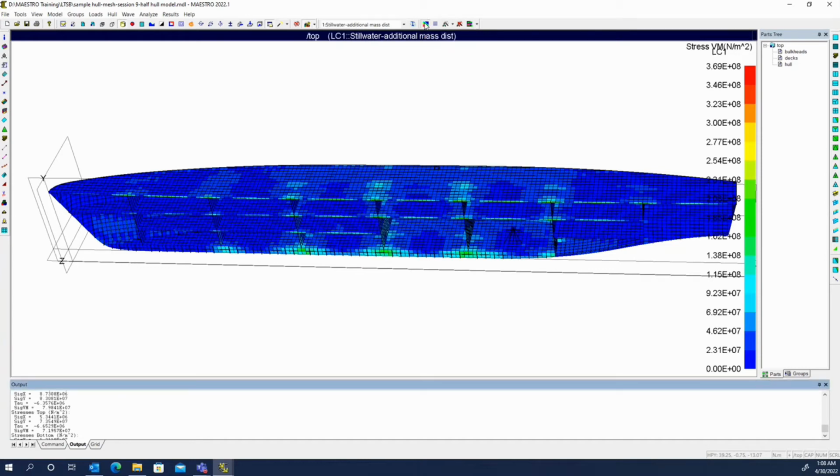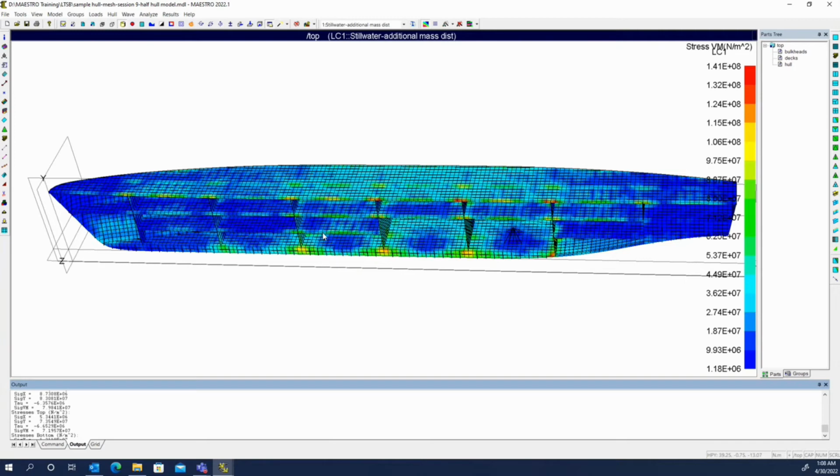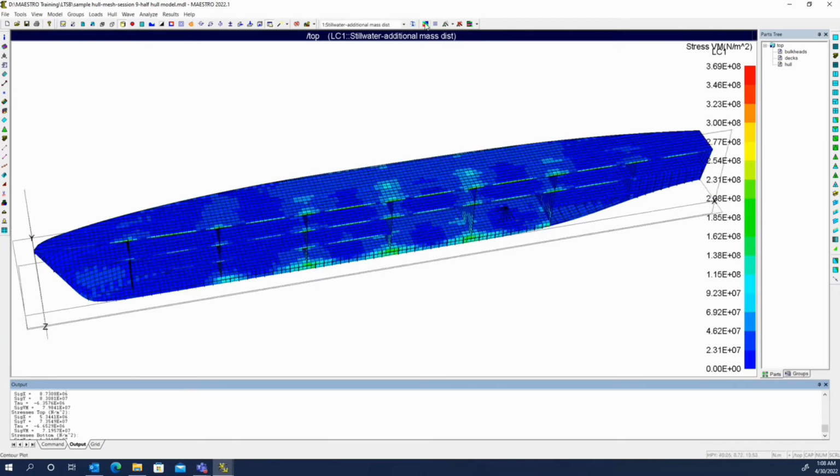We mentioned the contour button here to change the display of our stresses. Right next to it is a button for layers. If we click that layers button, you don't really see any effect on the model, no additional dialogues. If we do a dynamic query, everything looks the same. If we do a dynamic query now, yeah, it's von Mises midplane. We do layers, right click. Oh, it is a different menu, but there are no layers available.